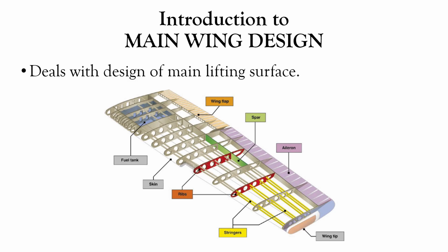The design of the wing consists of selecting the airfoil cross section shape, the average chord length, the maximum thickness to chord ratio, the aspect ratio, the taper ratio, and the wing sweep angle, which is defined for the leading edge as well as the maximum thickness line.